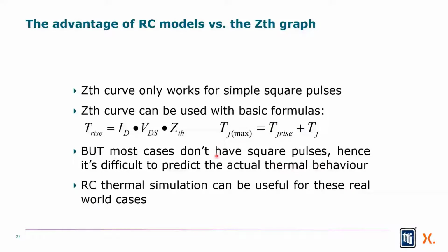However, if I get to really complex applications where I have sine waves and various duty cycles and things like that, it becomes very difficult or very tedious to calculate each part of the curve and add them all together. SPICE does that for us, though. All I need to do is input my complex wave shape based on my actual user application, and then when I'm finished with that, it will tell me what the output, what the performance of that equation is. So again, I can do thermal modeling with just equations and paper and pencil, but a SPICE model automates it and does it all for me.